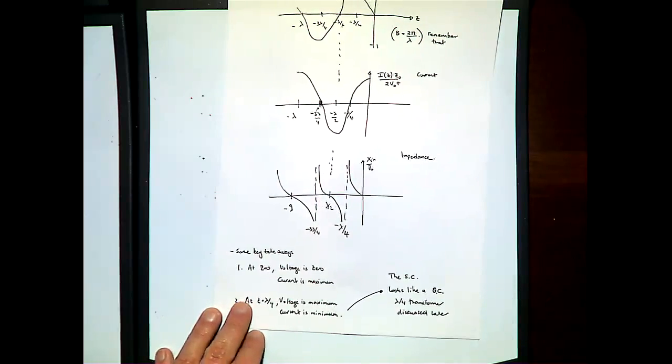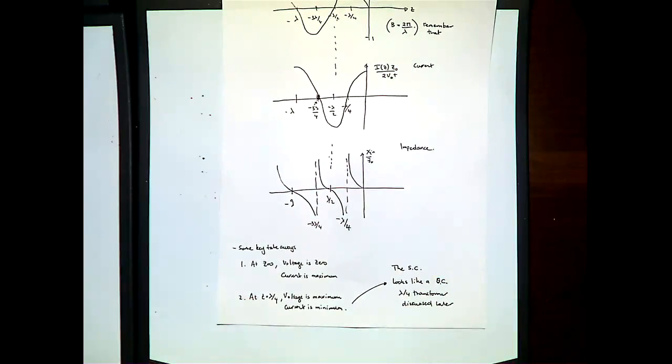Right? So essentially what it says is, using a transmission line, one of the key concepts here is that you can use a transmission line to transform the impedance of a particular load. And that's one of the tricks that we're going to use in our analysis in order to do impedance matching, when we're talking about Smith charts and impedance matching and various sections of transmission lines and shunt lines and the like.